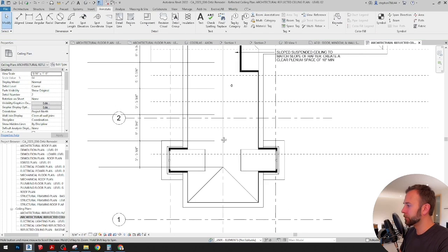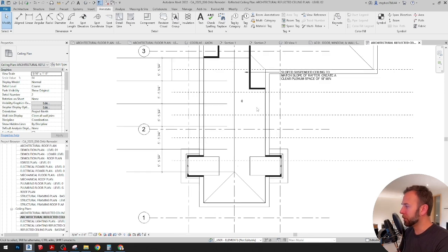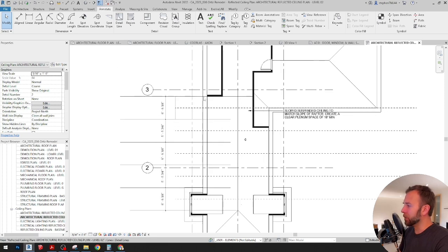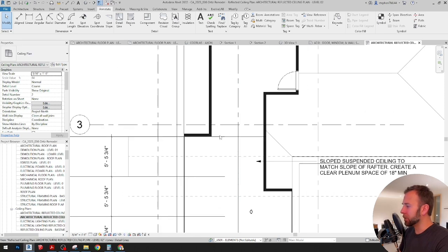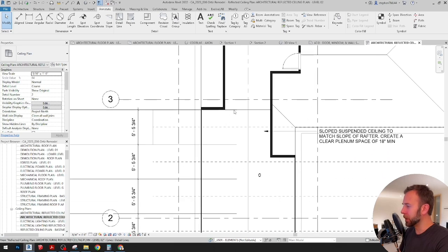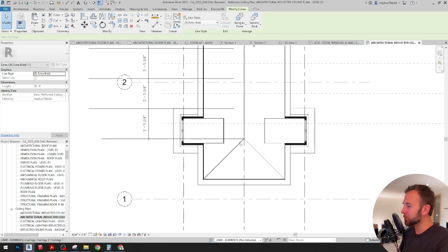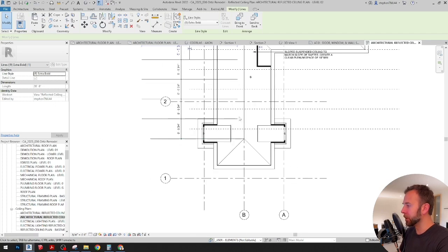So what I just did was, typically can lighting will be about 6 feet on center. So I found where the soffit cuts up in the existing bedroom here. So that's this line against this wall here. And then drew a line from the hipped gable peak, which is right there.